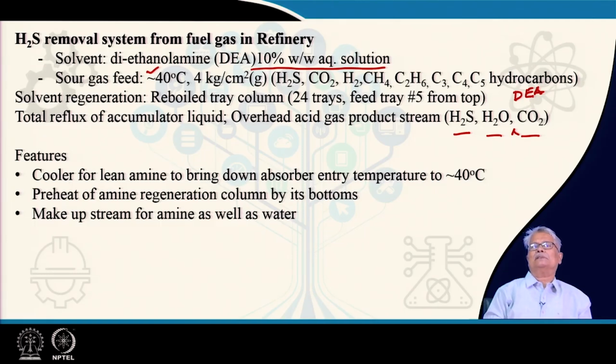The grams per meter cube of the solution being circulated would go up substantially, so this would require less circulation. So, you must choose a solvent which has high capacity, and to have high capacity you choose one which forms a weak bond.